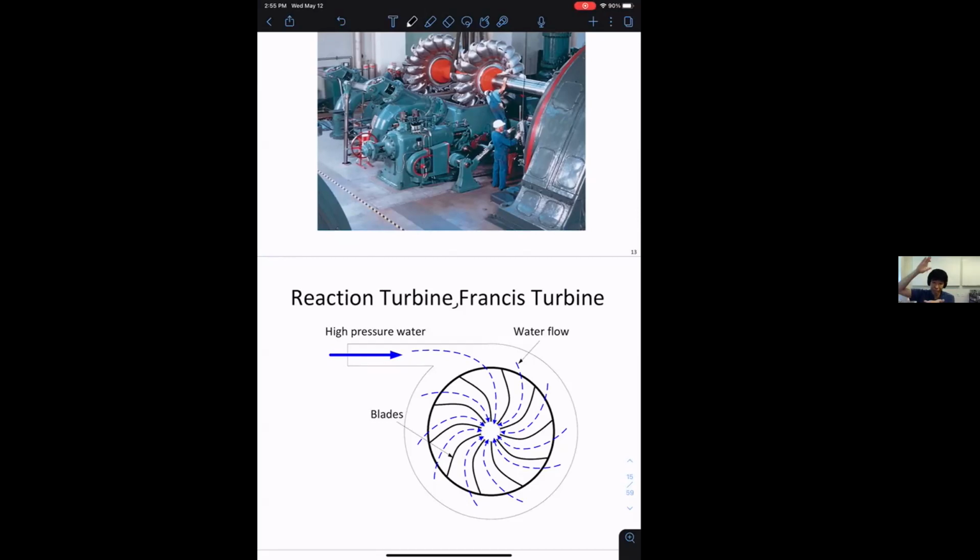Basically, what you do is you put the entire turbine in water, because I have a high flow rate, so this whole thing is submerged in water. Water will create a whirlpool effect once it joins anyways. So this will turn my turbine. Okay, so this is called a reaction turbine. You use this when the water speed is maybe not super high, but you have a large amount of flow, right? And so naturally you have a pressure difference across the blade, and this will turn the blades.